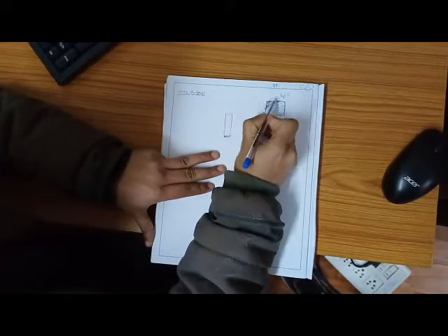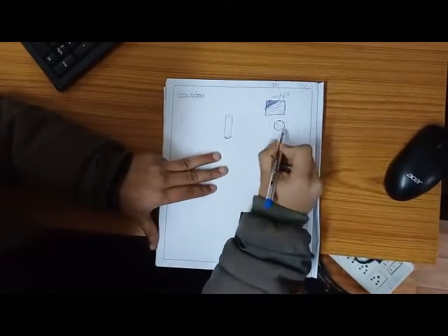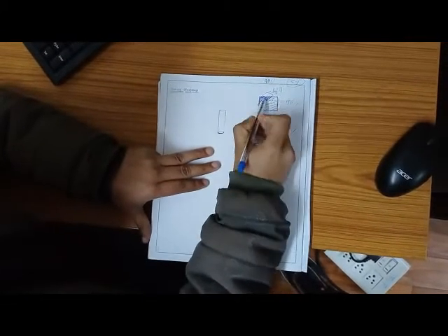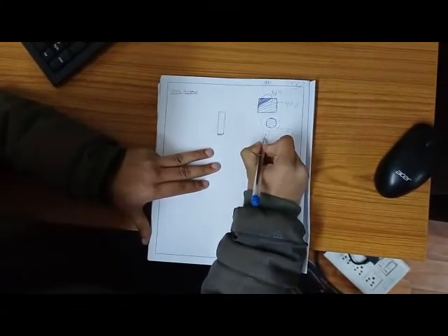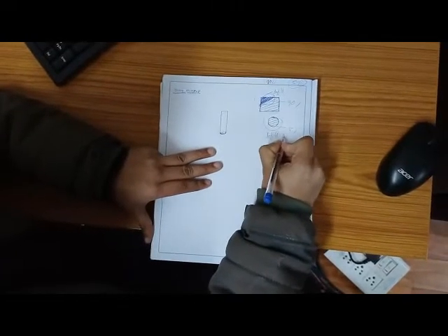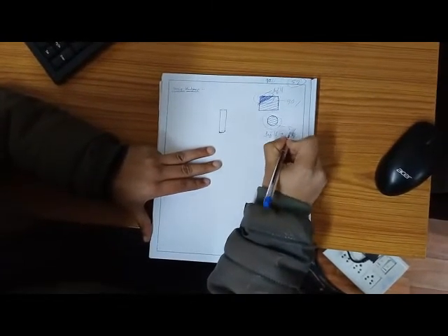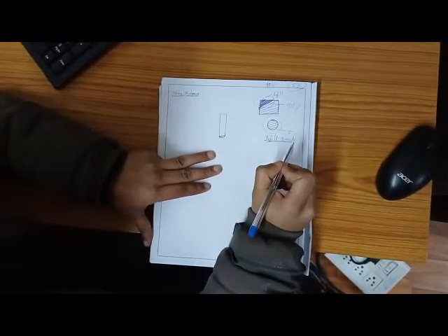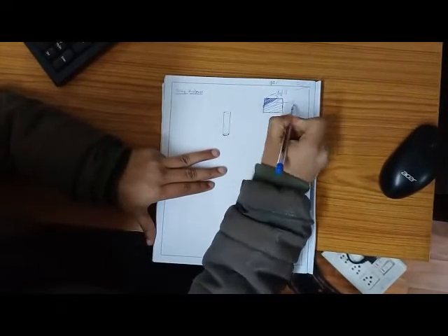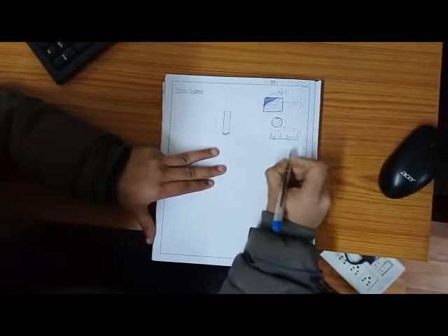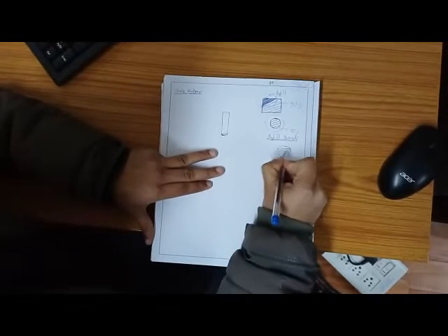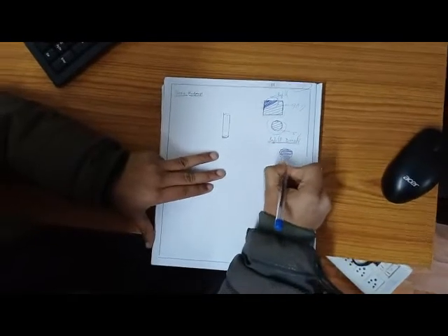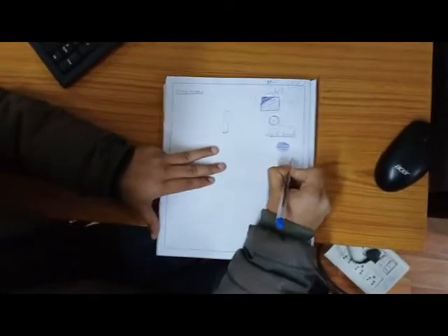So if you compare this section and this section, this is 5% and this one is 90%, so you can see the difference. This is called the infill density. Fine, infill density. How dense my part will be depends on how much infill density we are assigning. Talking about this one, this is 90%. Talking about this one, we have 5%. Talking about 100%, it will completely fill it. Completely the part will be covered, and this one we can call 100%.